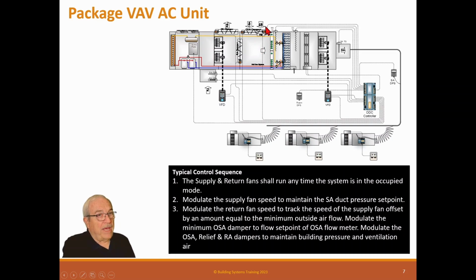If you don't have this minimum damper, it gets complicated. And the TAB guys have a terrific time with it. You have to set this damper up with stops.